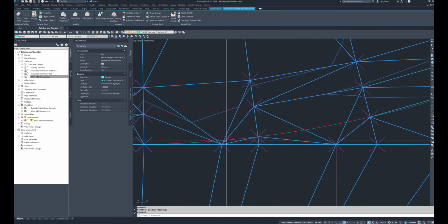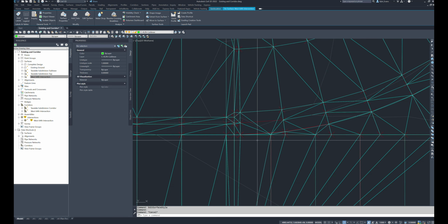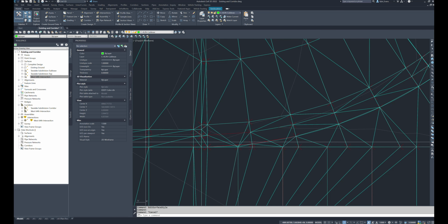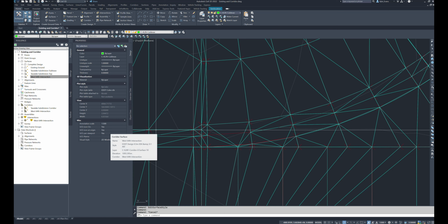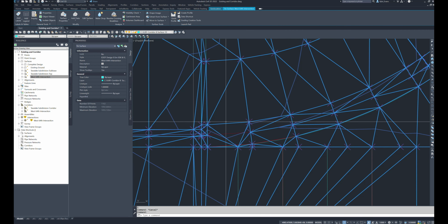And then we see right here, we get to this spot and they're not connected anymore. So that could cause us some weird issues. Bottom of gutter, the bottom of the gutter should carry along. It doesn't in here. And because we have two different curb and gutter widths, we have a residential gutter connecting to a straight face gutter. There's going to be a little bit of wonkiness in here as well. The easiest way to fix this, again, wait till your intersection is completely done. Wait until you're done rebuilding things, because as soon as we rebuild it again, the edits are going to potentially disappear.